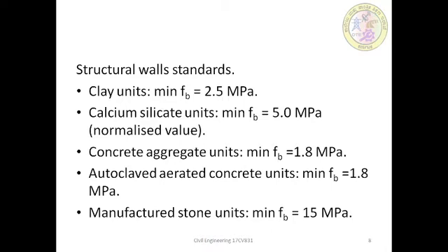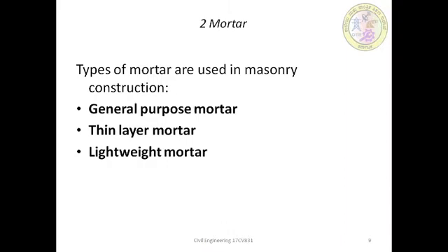If manufactured stone units are there, in that case the minimum compressive strength will be 15 MPa. So these are some standards which we can notice as far as the strength of the materials of the units is concerned.